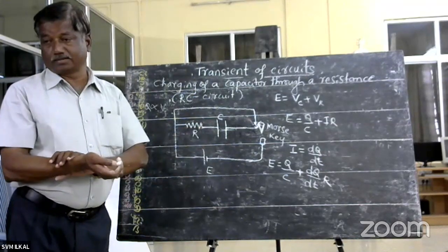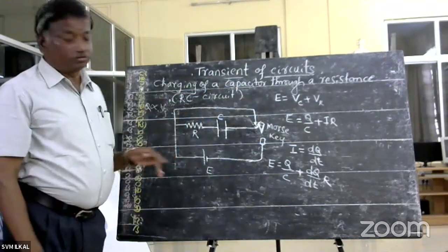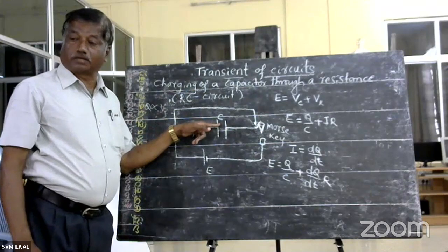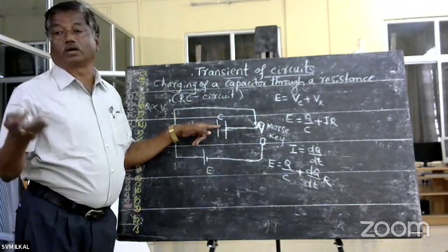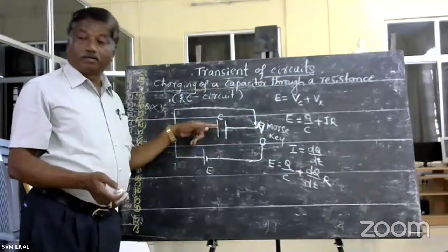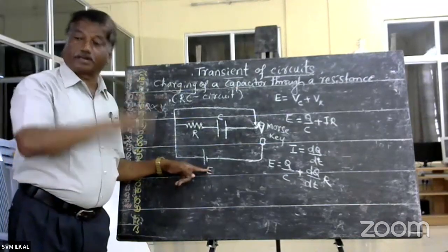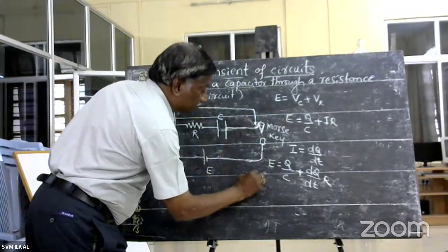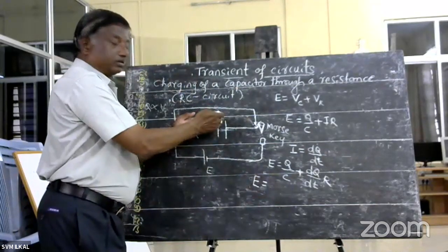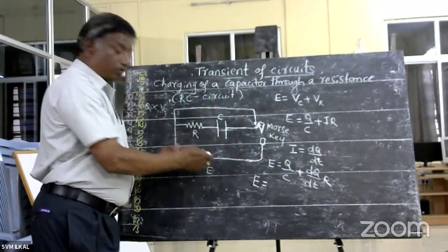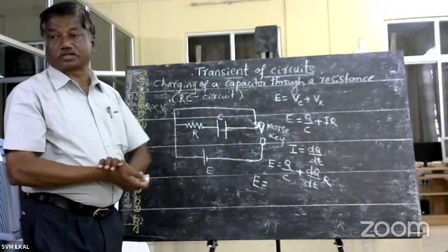That's why, as the current is switched on, the charge on the capacitor increases and the voltage across the capacitor goes on increasing, until it reaches the EMF of the battery, meaning the voltage of the battery. That's why after a long time, when the voltage of the capacitor is equal to the EMF of the battery, the capacitor is saturated to store the charge.